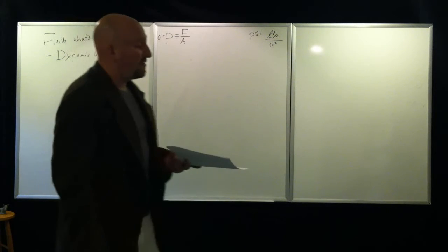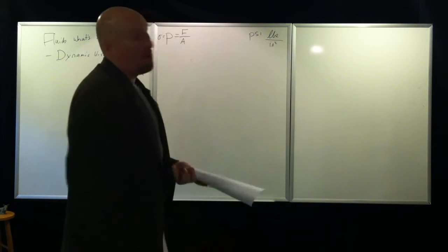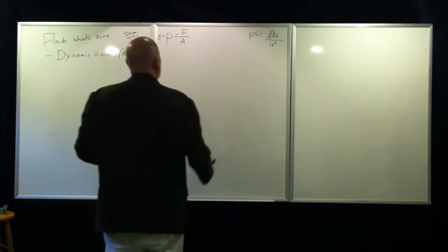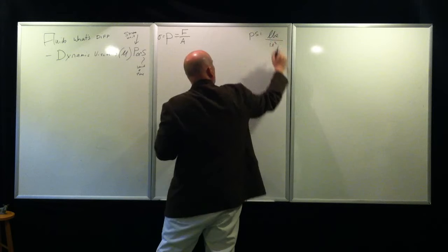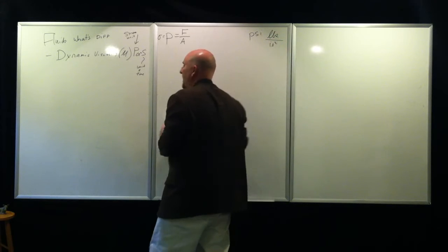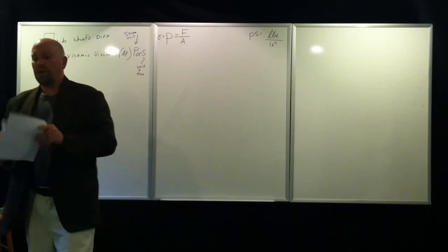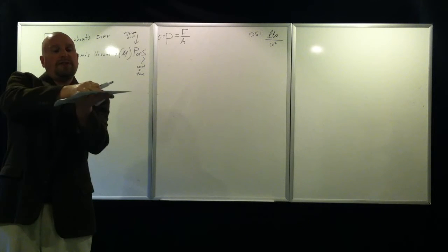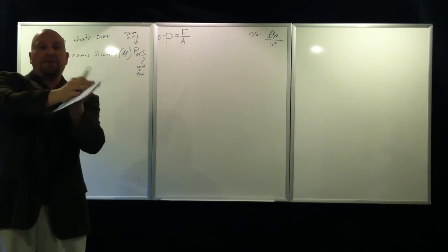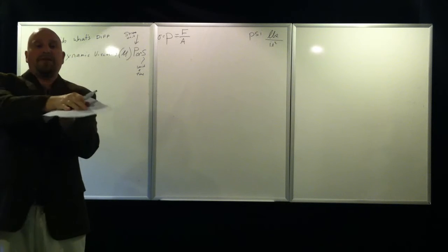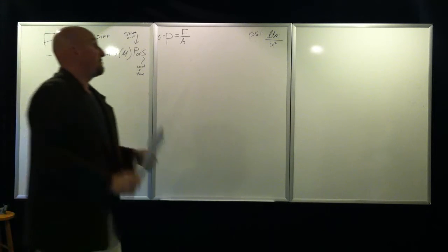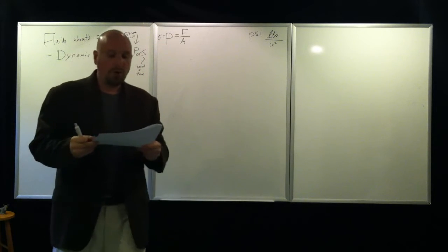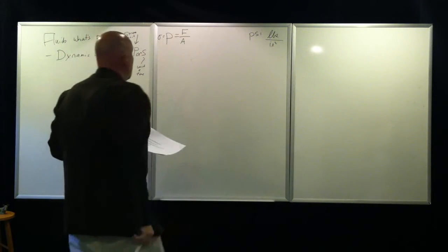Other units of pressure are atmospheres, pascals. Pascals are going to be mostly working in, say, the metric system. But, again, it's always a unit of force over an area that the force is applied to. Again, this is normal stress, but I can also put shear or tangential stress to see the result of this particular deformation. Different types of deformation depending on the direction of the stress compared to the area. It's an important difference. Alright, force.